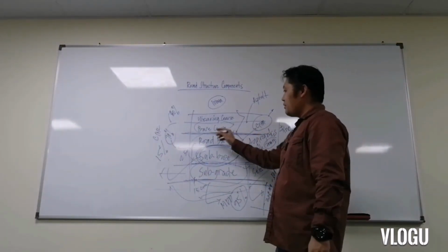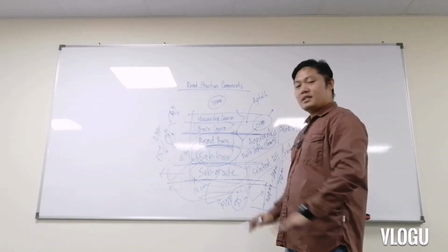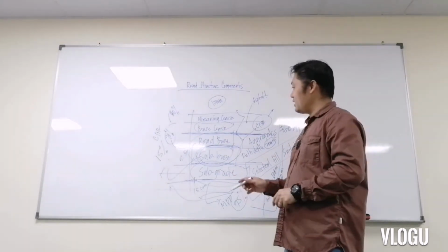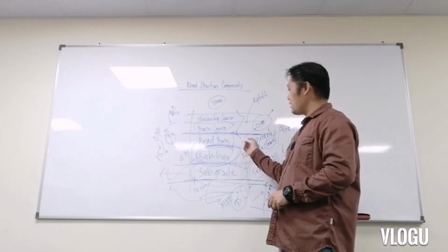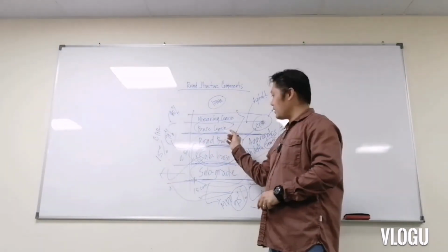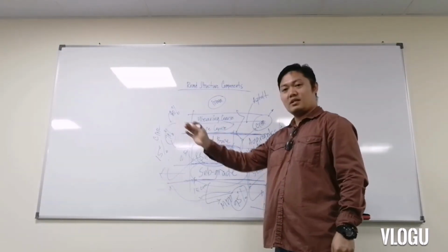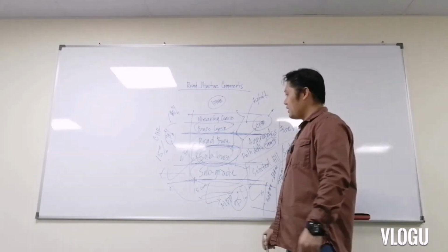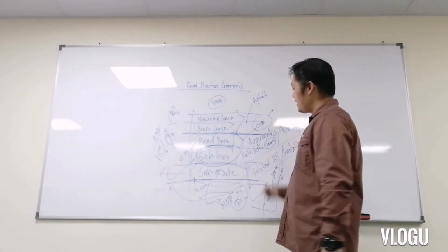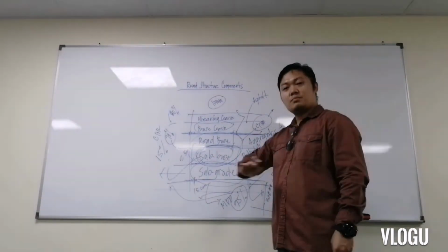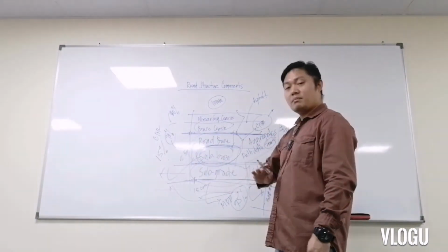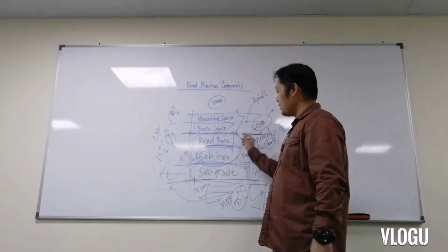So when we proceed to the laying of asphalt, when all the clearances have been done, verified and inspected by the project consultant, that's the time we can apply for the laying of the asphalt base course. We send the asphalt schedule and get it approved. And then that's the time we start applying the prime coat.